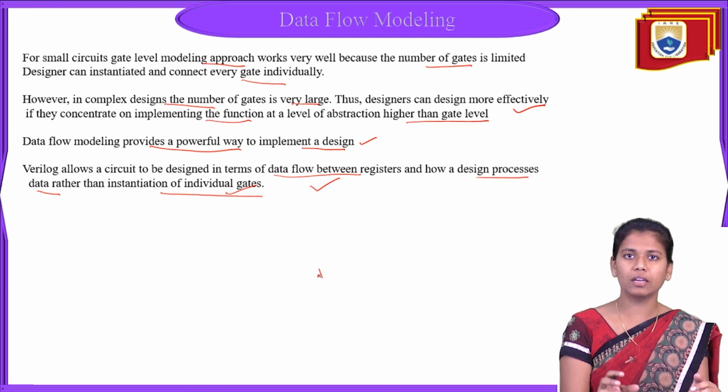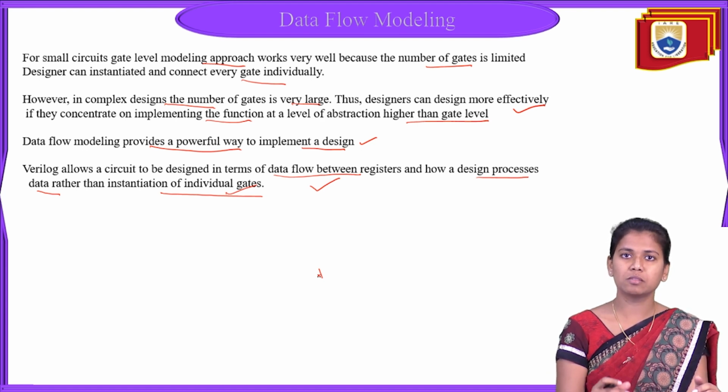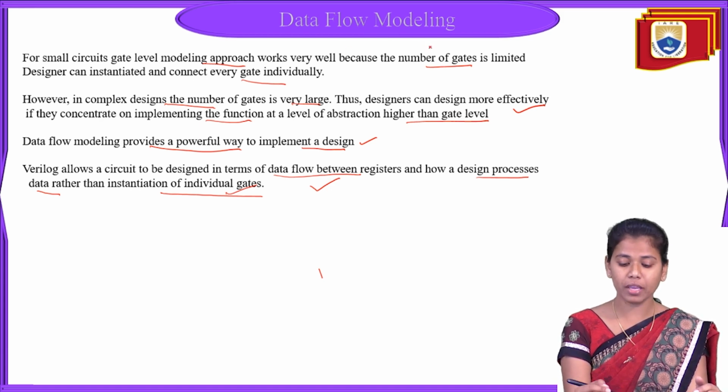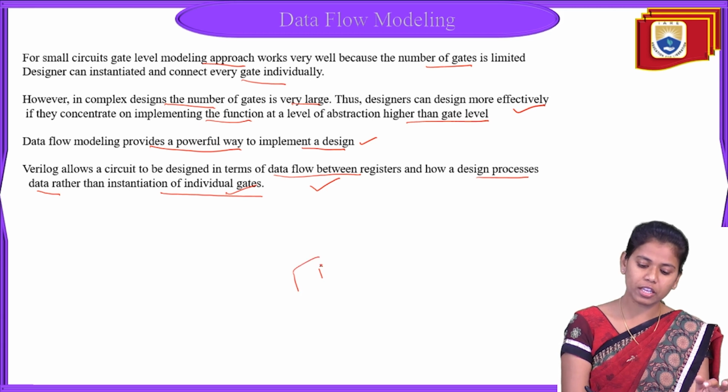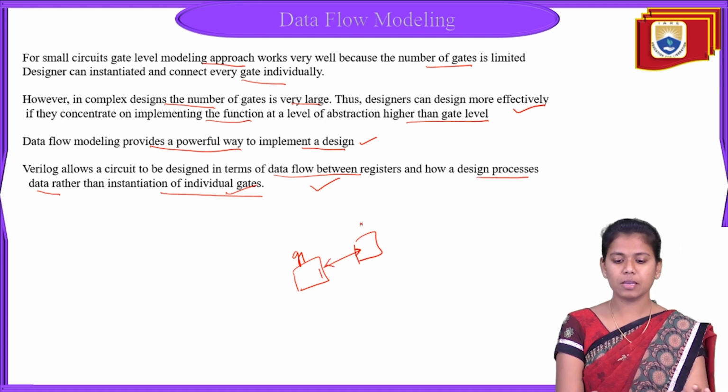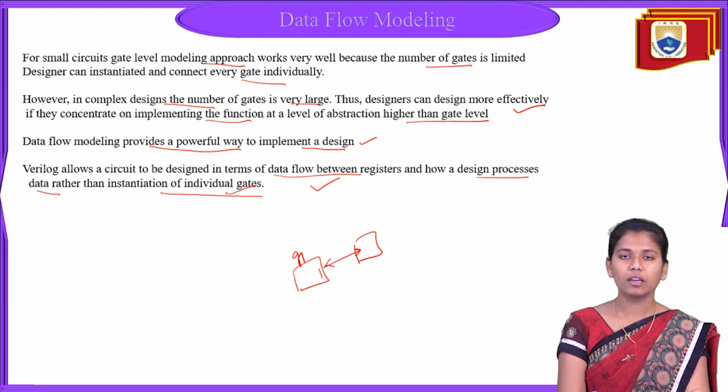Thinking about the process of each individual gate is much more time consuming. To avoid that, data flow modeling helps us design complex electronic circuits. Data flow between registers is carried out very easily when compared with considering each individual gate and the communication between two gates. This is about data flow modeling.